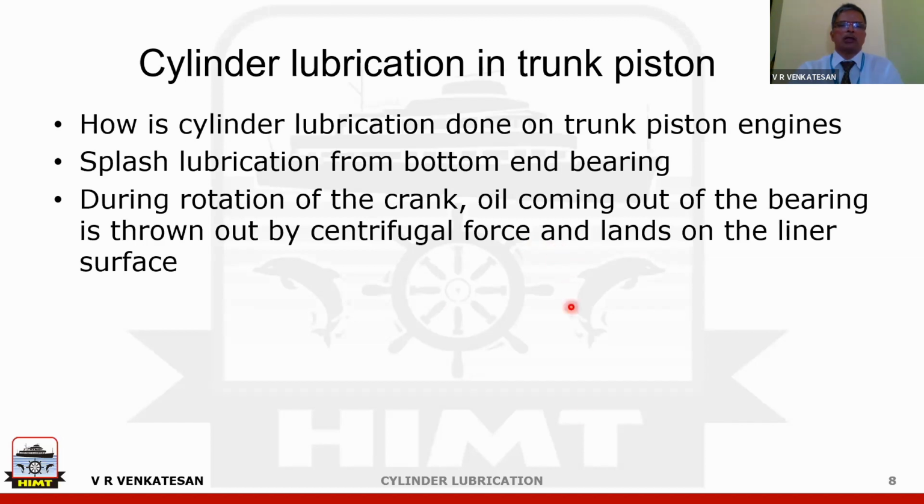So the rotation of the crank, with oil coming out, is the part which is going to splash oil onto the liner. So splashing does not mean the crank dipping into oil. It is not like that. It is because of centrifugal force. And this oil will be quite a bit.